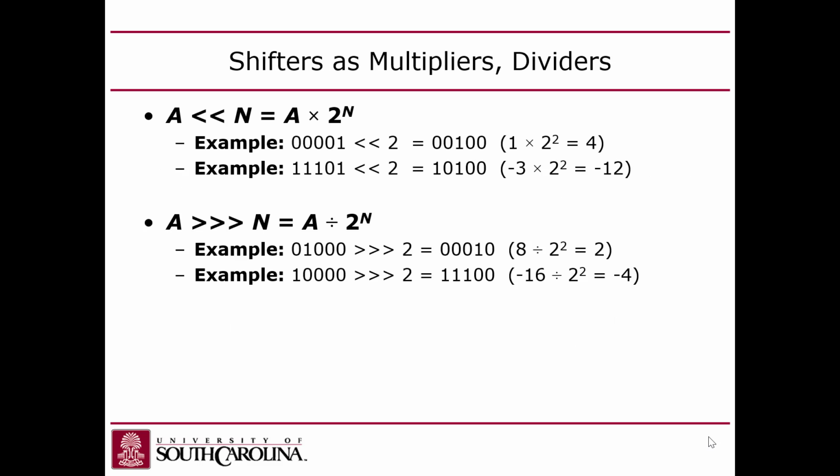All right. Okay, so shifters, what do we use shifters for? Shifting is a fundamental bit manipulation operation. It's also the way that you build multiply and divide operations. So if you shift to the left, you multiply the value that you're shifting by 2 raised to the n power, where n is the number of bits you shifted, right? Do you guys cover this in 212? Probably talked about this before.